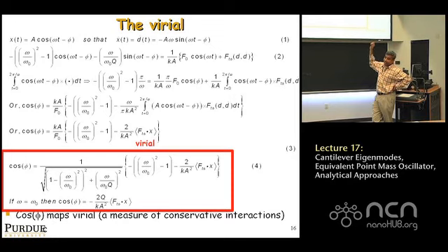All right? And it's integrated from 0 to 2 pi over omega, so I can take the average value of that over the cycle. That quantity in pointy brackets is basically tip sample interaction force times position integrated over the cycle.